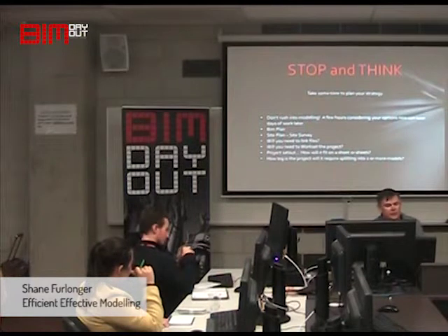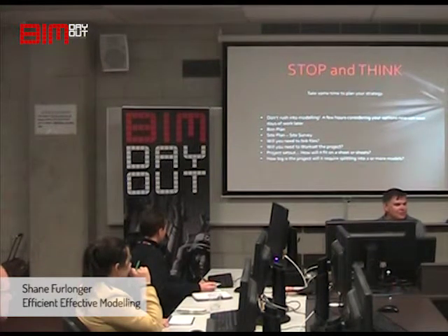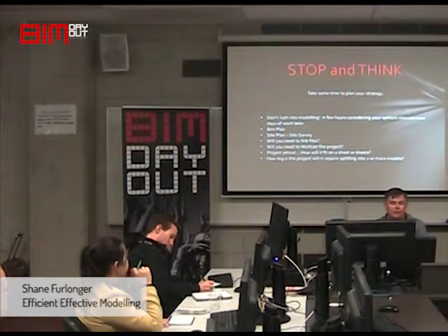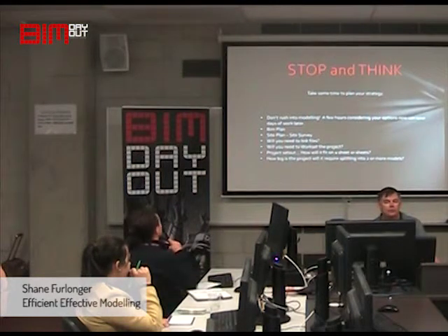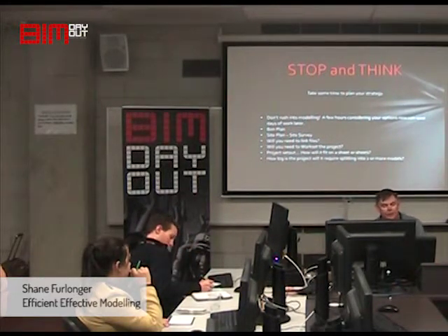I just opened a project the other day that had 30 work sets in it. I almost fell off my chair. Don't go to that extreme. You should be able to get away with maybe 10 work sets, depending on how many files you link in. I like to have a work set for every Revit file I link in. CAD files I normally just put on one work set, just called CAD files, because you either want them on or you want them off, or you want to load them or you don't want to load them.